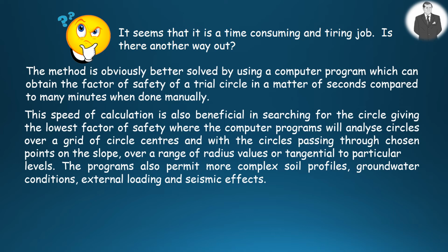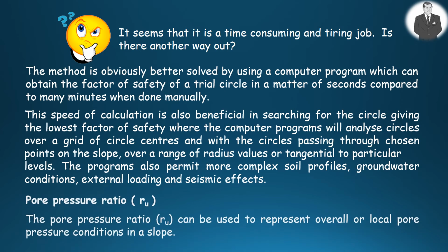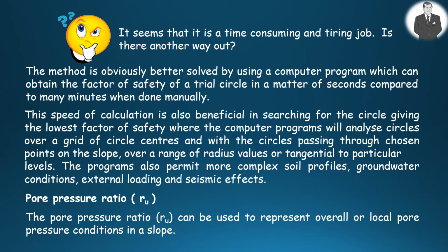The programs also permit more complex soil profiles, groundwater conditions, external loading, and seismic effects. The pore pressure ratio can also be used to represent overall or local pore pressure conditions in a slope analysis.